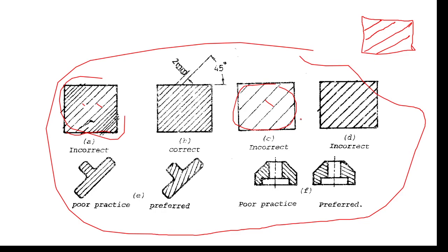In AutoCAD, it is not so straightforward. We use the trial and error method. Well, we create the hatching lines, okay, if we cannot find them suitable in their space value, then we make another trial, changing the space value.